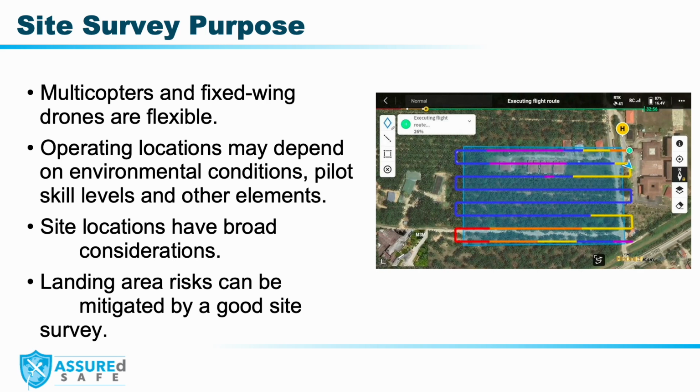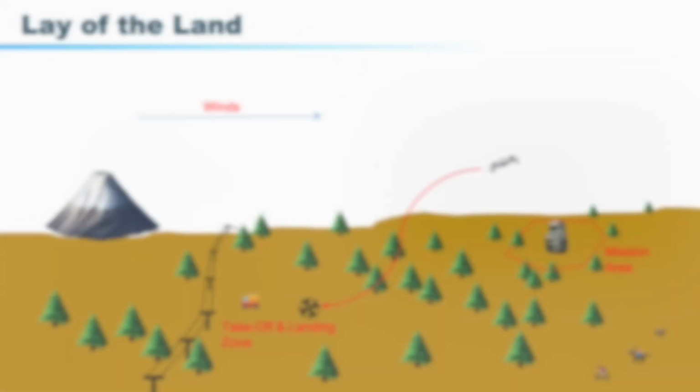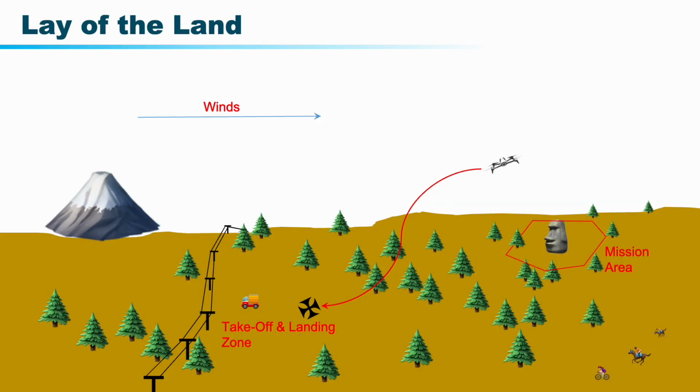As an air boss, you might be coming into the mission after a site survey, or one may not have occurred. For complex missions, it is critical to understand the area and know the hazards. You should understand the lay of the land from the mission plan and site survey. From that basic understanding, it is helpful to identify any obstacles and either estimate or measure their range and height. Know the indications of power lines, buildings, and unusual parts of the terrain.